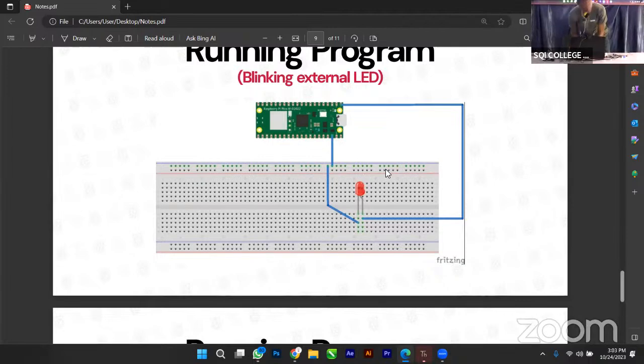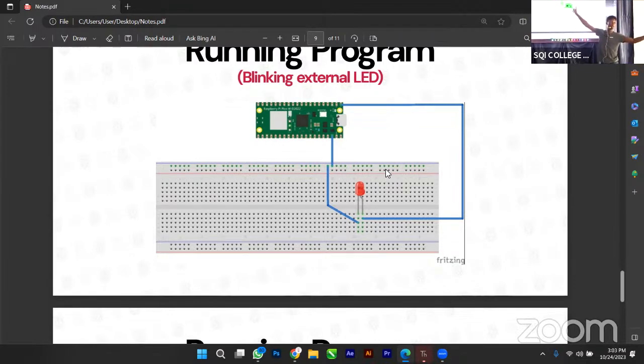Do you know how to connect it to the positive of the LED? Now, this is GPIO 0. Look up, everybody. This is GPIO 0. This is the long side of my LED. If I connect GPIO 0 to any other rail here, it means GPIO 0 and the positive are connected together. Do we understand? I said that everything here is connected together, yes?